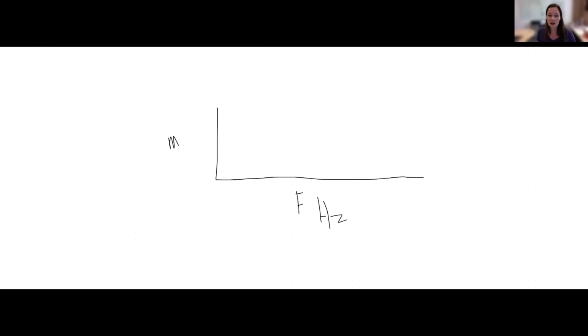Okay, so what we're going to do is compare some different filtering settings for filtering EMG from an example data set. This data set is a little too clean to be a good example almost, but it's what I had handy, so we'll just use it anyway. We're going to design a high pass filter, which means, like we said, we're going to filter out low frequencies and keep high frequencies.